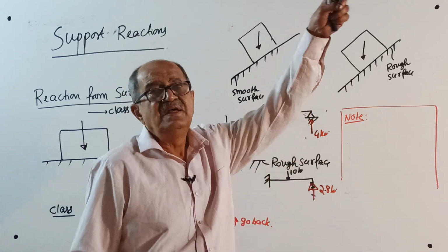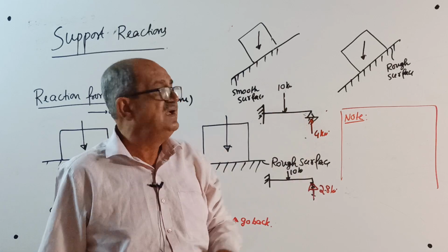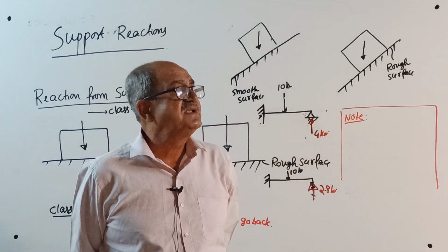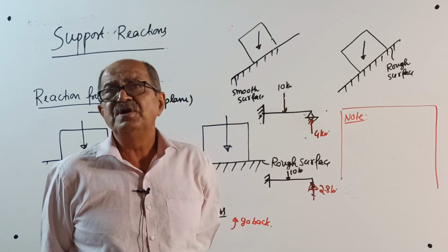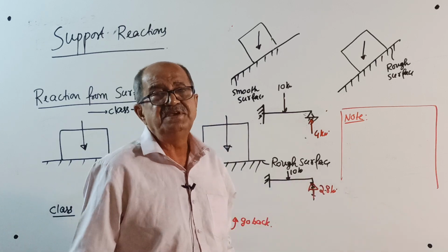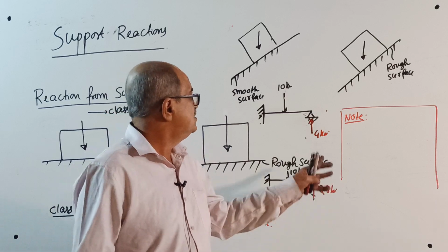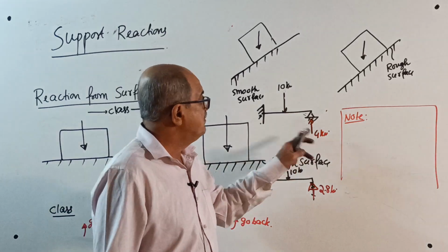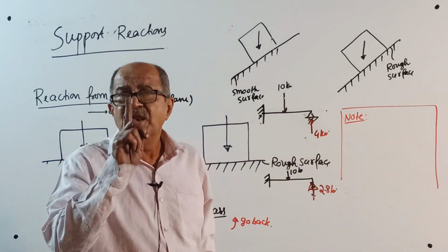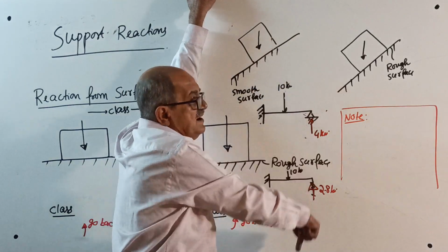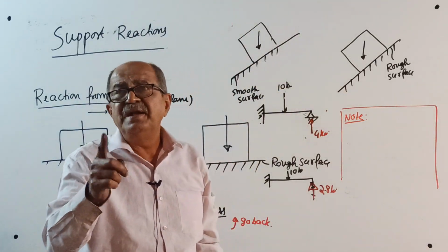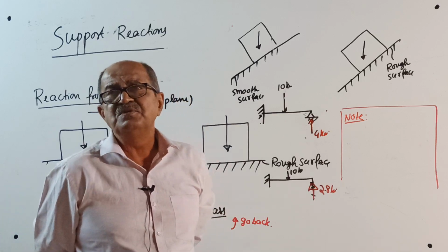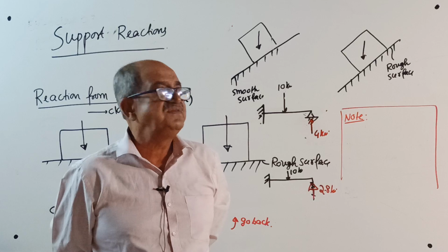That is because that was a statically determinate structure, and this is a statically indeterminate structure. For a statically indeterminate structure, reaction depends upon displacement. This much is not required for you. I just told it for those who have good structural knowledge. What happened is, reaction will come when displacement is either fully prevented or partially prevented. The partially prevented case will come when you go to structural analysis.